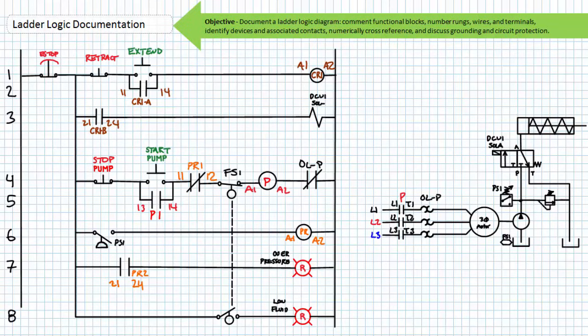The terminals of all the logically interconnected coils and associated contacts have been numbered. The solenoid and pilot lamps will use whatever terminal numbers specified by the manufacturer. Let's just say they're 1, 2. Be aware that DC pilot-operated devices may be polarity dependent. If so, a manufacturer will indicate what is the intended high and low side.